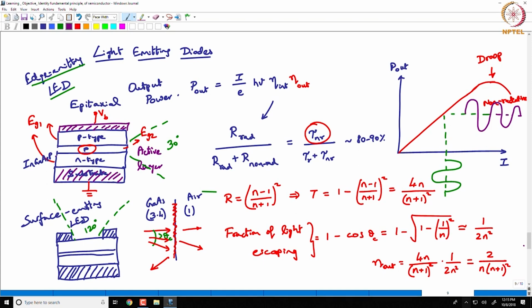And if it is done at high enough speeds, if you modulate it at 1 hertz, 1 cycle per second, you can probably even sense that the light is actually turning on and turning off. You can see the blinking, but if that is happening at 100 megahertz, right. So, the time period corresponding to 100 megahertz is 10 nanoseconds. Your eye is not going to be able to make out that there is any change in the intensity, right. It will look like constant intensity to us, but it is conveying information. You can start conveying information through that.